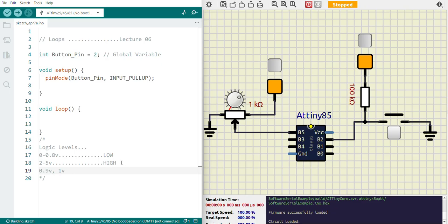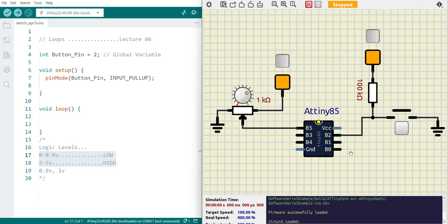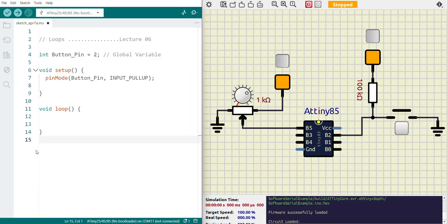So to make sure we have a high or low, we either pull up a GPIO or pull it down. We will see the pull down part. It depends on what you're doing. Logic levels are very important. For those who didn't understand digital electronics very well, I can only make quick recaps.